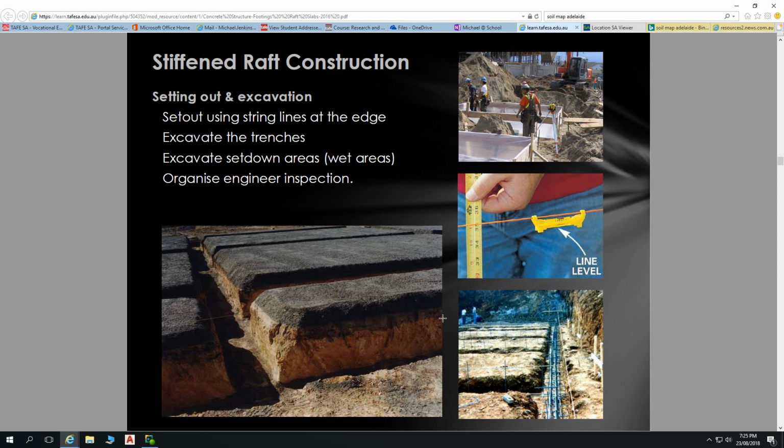So you're going to have to be spending more on your concrete, but also you have to do something with your soil as well. When you excavate, now I'll try to remember how much this guy told me he excavated his footings and had to find a place for. I think he said it was 50 cubic meters he dug out. Yeah, that would be right. 50 cubic meters he dug out from a site and had to put it somewhere. Couldn't put it on his site, small site. You think 50 cubic meters, right? What's that going to weigh? It's got to weigh like a shade under 100 ton. So 90 ton of soil or so.